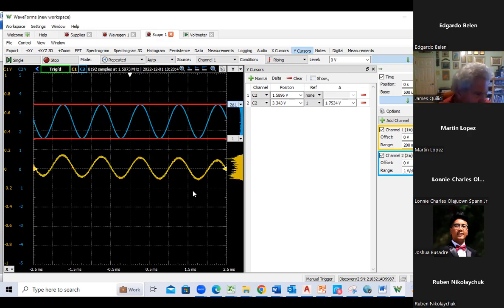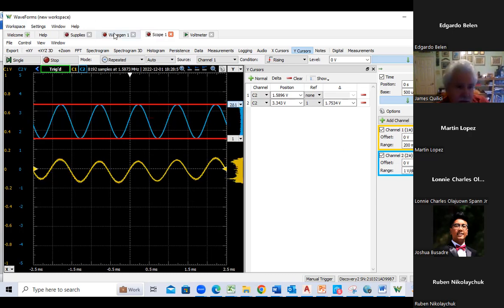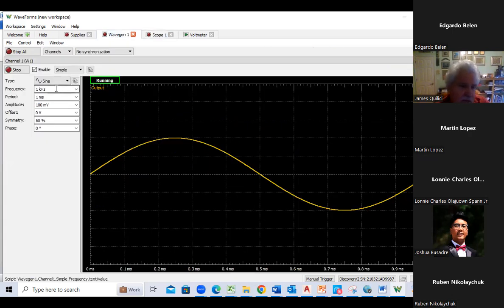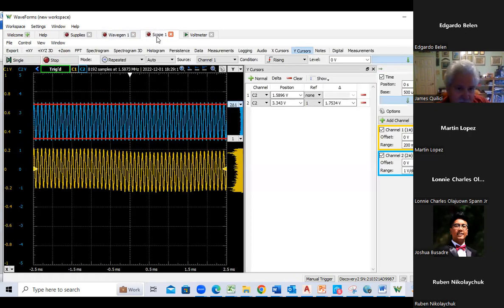Okay, so step 9, it says locate the midband range. Right now we are running at, let's see, oh, we're only at 1 kilohertz. That could actually be somewhat of a problem. We should probably be up around 10K. The reason I say that is if our capacitors aren't large enough, we may not actually be in the passband. Let me go back here and look at this again.